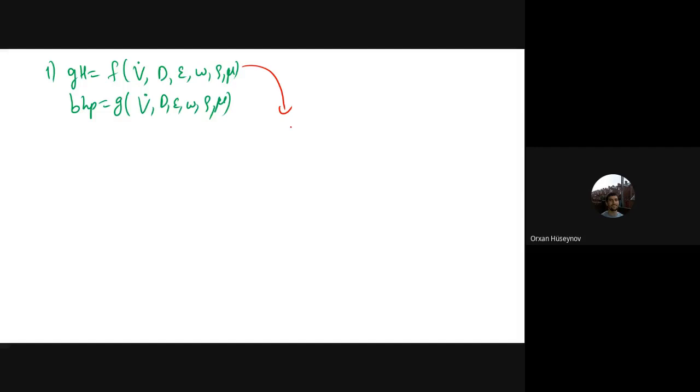So the number of variables n is 1, 2, 3, and 3 more and 1 there: 7 variables. And for the primary dimensions, j, I will write 2. But firstly, let's find the dimension of GH, which I will leave for you, and for V dot, the second one, the dimension is volume divided by time.